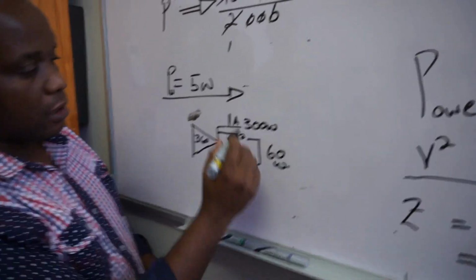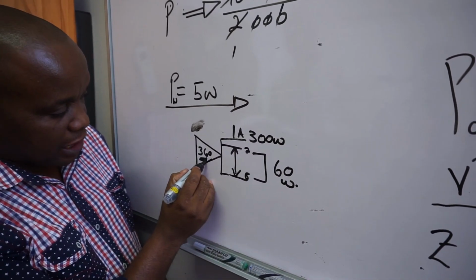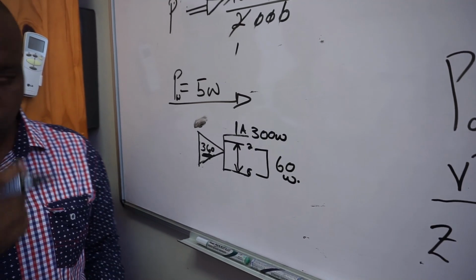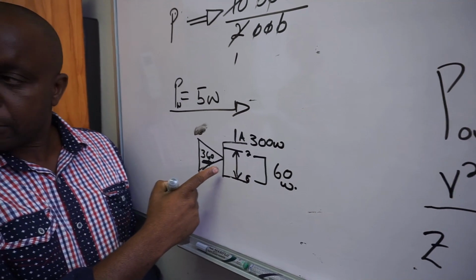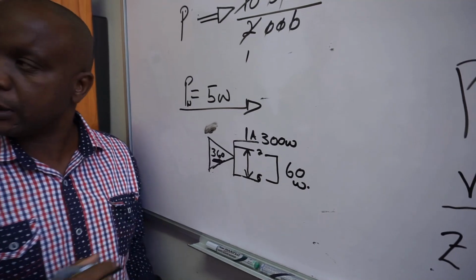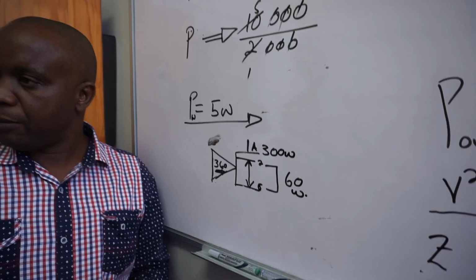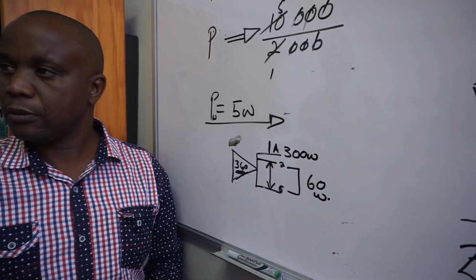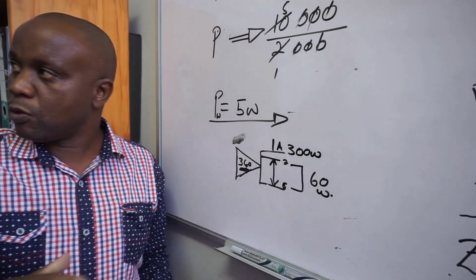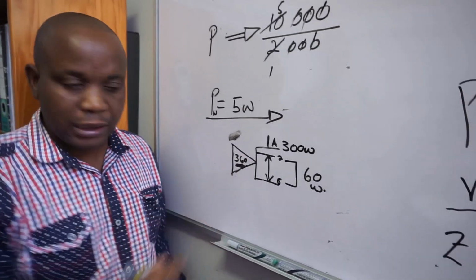If anything, if I add my totals that I've measured with the impedance meter, and they go above what the amplifier is capable of producing, I'm definitely overloading the amplifier. Most amplifiers will, on instant, switch on, they will play, then you will see it goes to red, it goes into protection mode. You force it, sometimes when you play soft music, soft volume, you find the amplifier will play for a few minutes, then it cuts off. Or you let it play at soft sound continuously, then after a little while, when the amplifier is warmed up, it can cut out. Because remember, impedance is reactive.